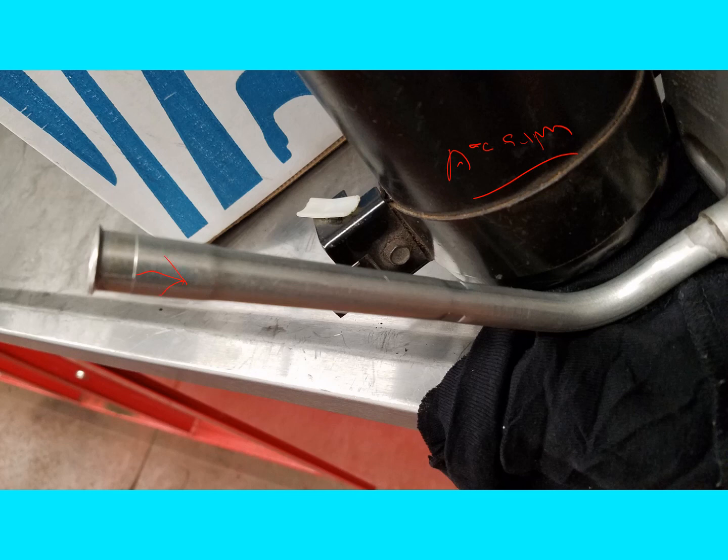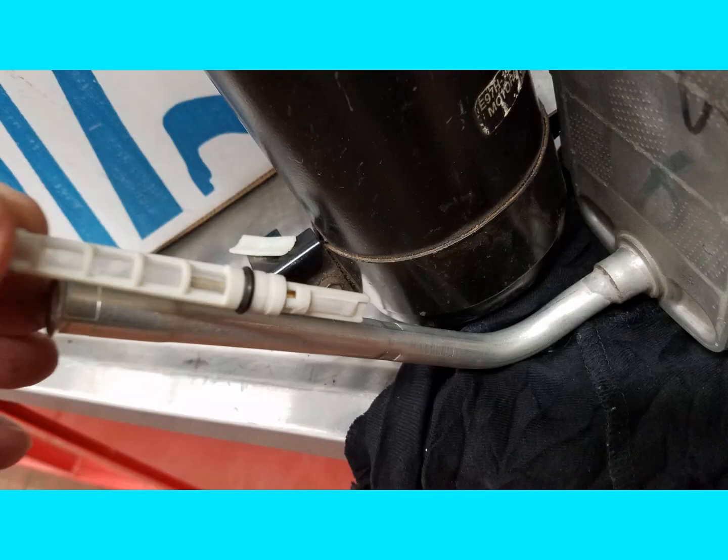Something to look for to see the location of an orifice tube is a crimp somewhere right after a connection or right before a connection. You can see right here we have some crimping. That's so the orifice tube can't slide beyond that point. It's designed so it would be held right in this tube. So the orifice tube would slide in this direction. This would be the direction of flow. The orifice tube is going to go into that evaporator core just like that.